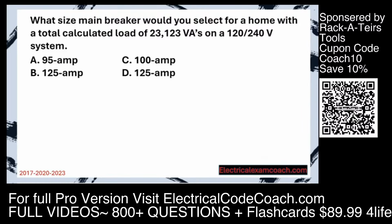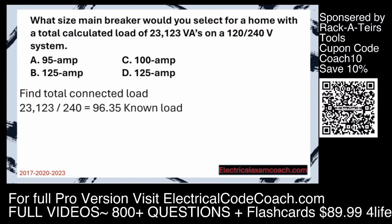What size main breaker would you select for a home with a total calculated load of 23,123 VAs on a 120/240 volt system? Step 1, find our total connected load. Well, they've already done the load calculation for us, so all we have to do is take our total known VAs and divide it, and that's going to give us our load in amps. And in this case, it's 96.35.